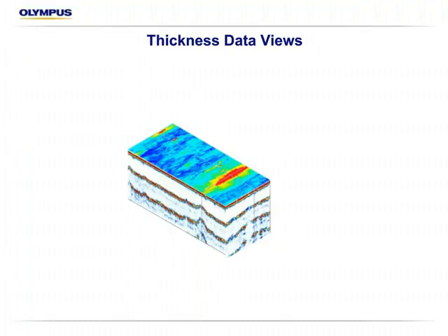A lot of corrosion is more important because of its volumetric extent. So by using the side views and the C-scans, we're able to put cursors on and get those measurements volumetrically. It's also very helpful if we do have something like mid-wall laminations, to determine if they have any cracking or stepwise cracking in between them, or any other condition besides the thickness reading that might be useful. These other views really come into a big benefit for that.